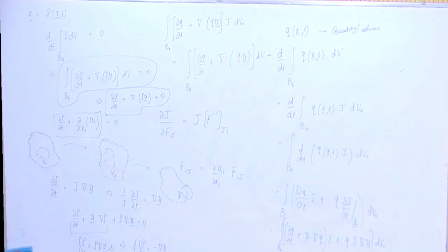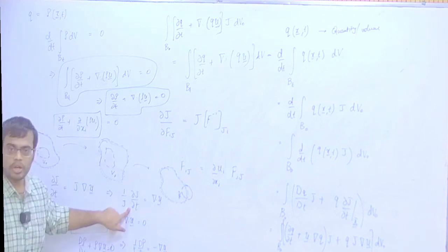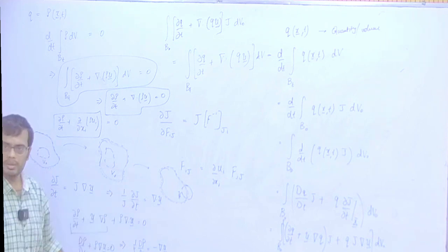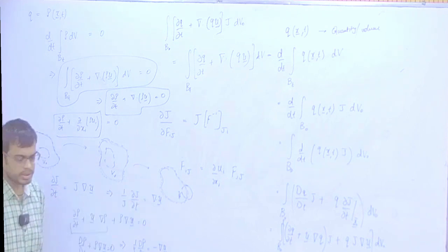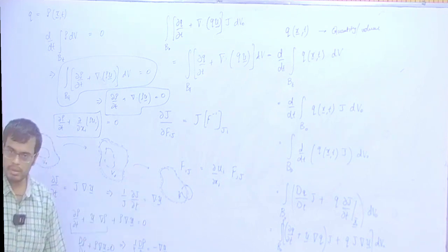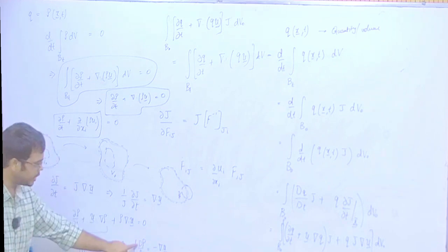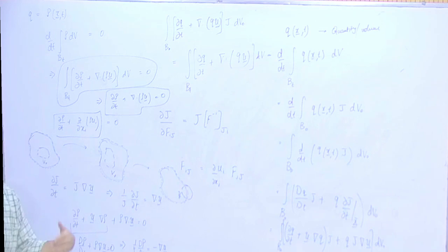So if ∇·u is positive, then your fluid is expanding, the volume is increasing, and if the volume of the whole fluid is increasing, the mass of the whole fluid cannot change, so the density is decreasing. Let us say you have an isolated blob of fluid that is contracting. For that, ∇·u will be negative, Dρ/Dt will be positive, and vice versa.